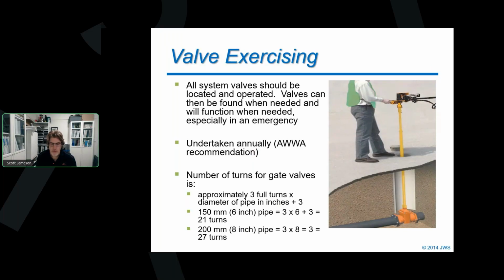I want to make sure that it's going to work when I'm going to do the flushing, right? I don't want to set up all my gear, send out all my notices, be there ready to do this flush, and then realize that, oh, this valve is seized and I can't close it, and therefore I'm not going to be able to achieve the flushing that I thought I was going to, right? We want to go out and do that first and make sure that everything's going to work for us.